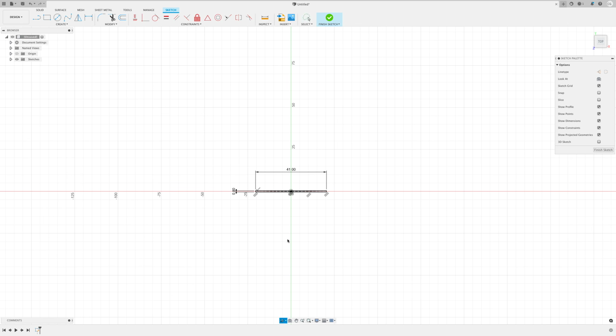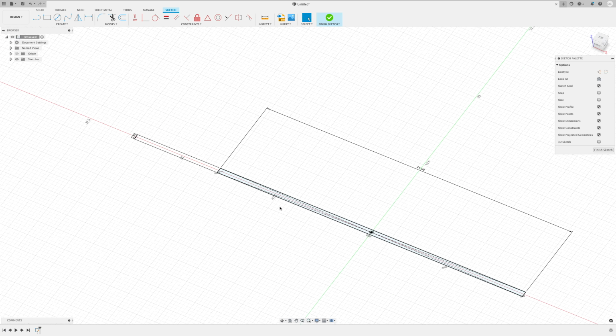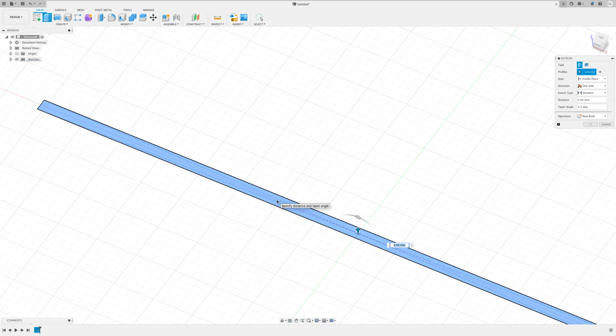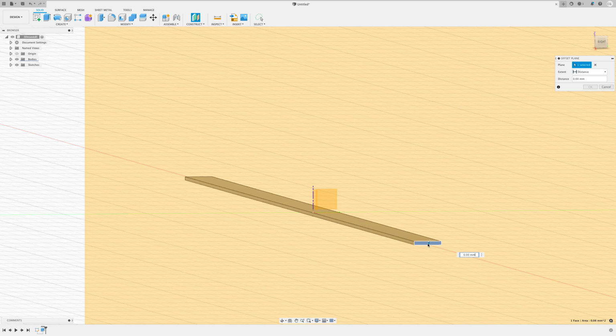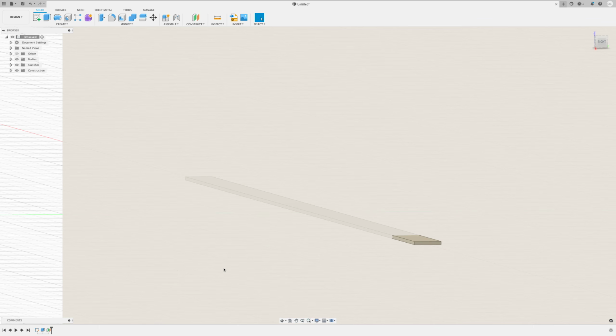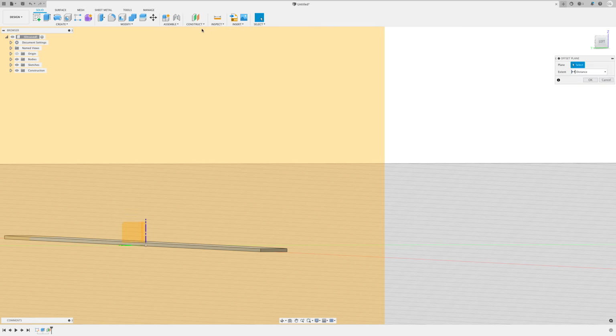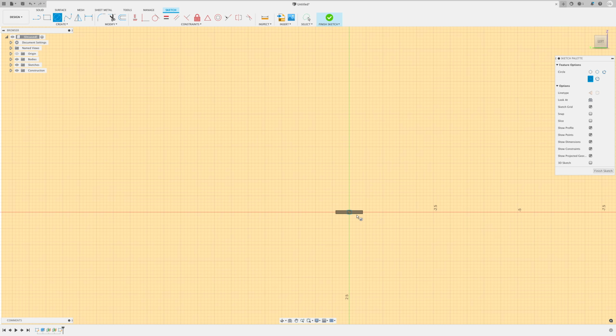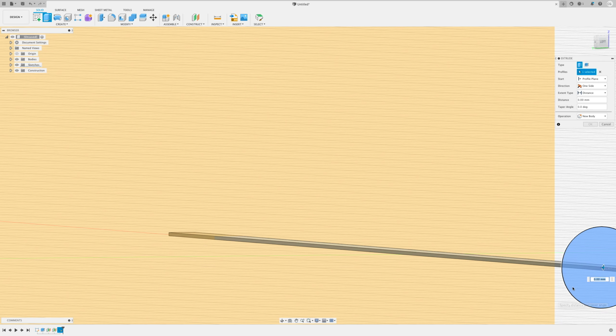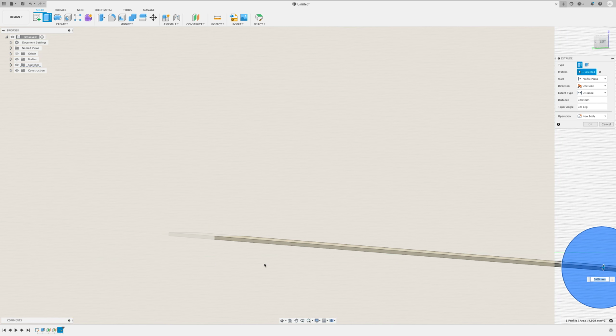As always in Fusion 360, we start off with a sketch. I'll make one for the connectors that stretches the whole length of the device and just extrude it by a very small amount. To position the body of the filament in the correct place, I'm creating an offset plane from each end of the connector. I can now create a sketch on one of these planes with a circle of the required diameter. We can then just extrude this to the other plane and that's our body.